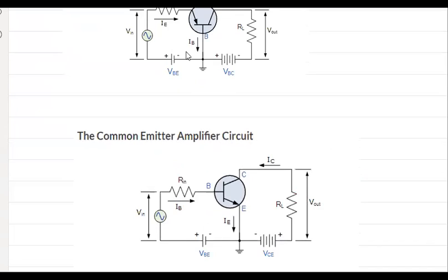Now these are the parameters that you should remember. Remember this structure, right? Obviously, we cannot have a circuit without resistance, because then we will have infinite current, which is not desirable. So the resistance between your collector and this common emitter is called your load resistance.